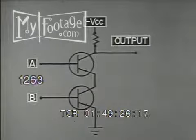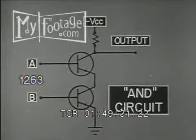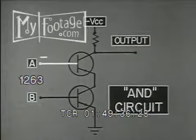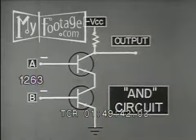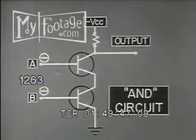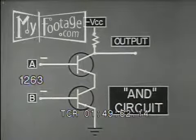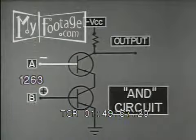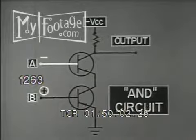Here's another example. This is called an AND circuit because it delivers an output only when both input A and input B are present. The circuit consists of two switches in series. When both inputs are negative, current can flow in the load. If either input is positive, the corresponding emitter is reverse biased and the circuit through the load is interrupted.